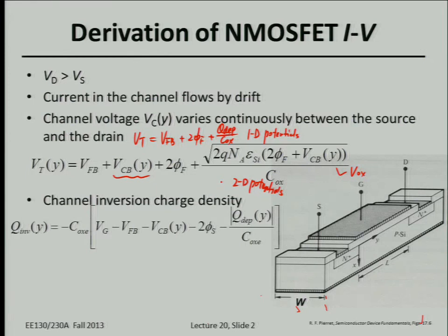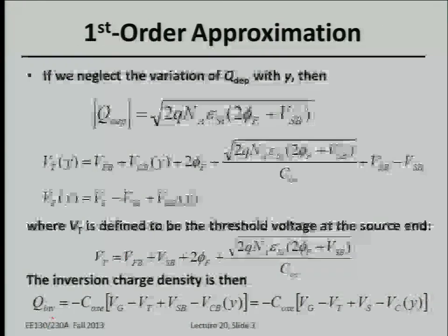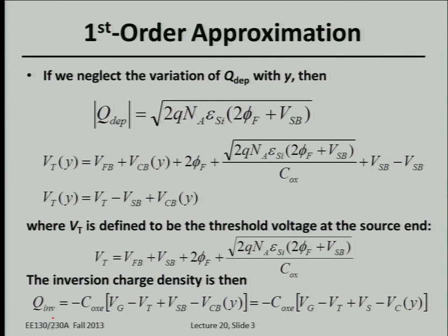Okay, so the inversion charge, which is just gate capacitance times gate bias subtract Vt, is a function of distance along the y direction. So we're expecting to see a quite non-uniform distribution of inversion charge, which has to be balanced with depletion charge. Okay, so all these facts tell us we need to re-derive the threshold voltage expression for the MOSFET once we take into account the actual potential contribution from the lateral direction, once we deal with these two-dimensional potential profile problems.